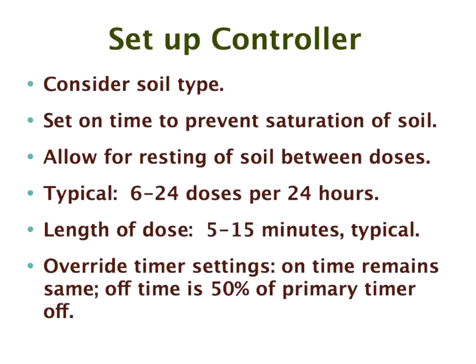Setting up the controller. Okay, the soil type is critical. The heavier the soil, the shorter the pulse, the shorter the time. So in a really good soil, you might run the system, say the system's got to run for 2 hours to get the amount of effluent out.